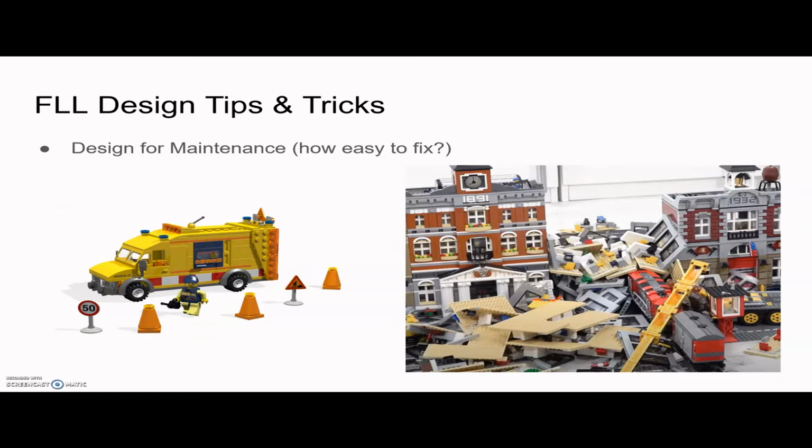No matter how well you design your robot, you'll have pieces fall off, shafts twist and bend, and wheels wear out. For the first line of defense, choose designs that don't break as often. Sturdier is usually better. Then, for things that are likely to twist or break or wear out, ensure that it's easy to replace those parts. For example, if you need to change your wheels a lot, don't put a big case around them that you have to disassemble just to get to the wheels.